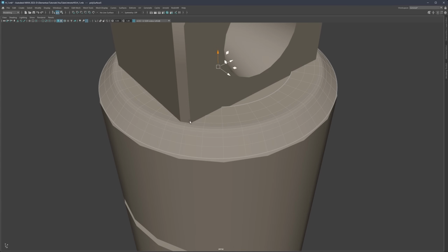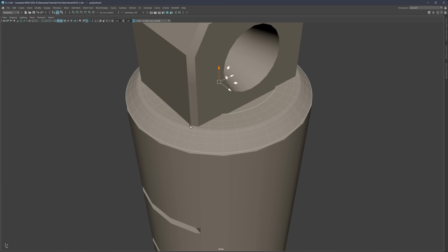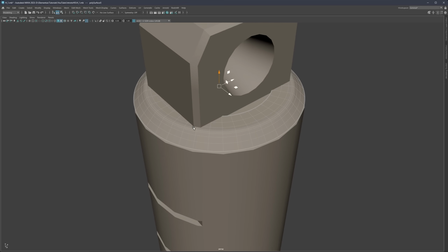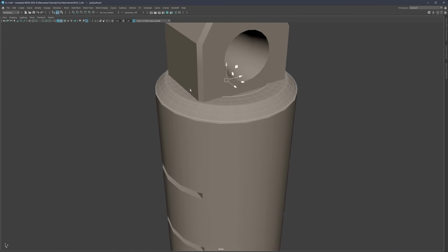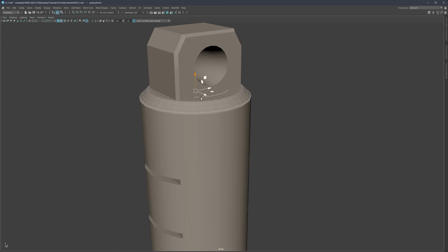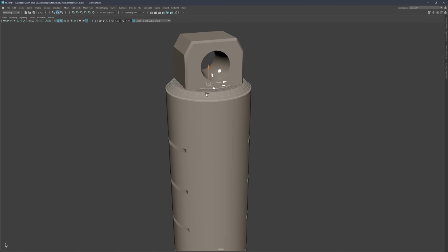And if you remember, what was the distance before that we established, that we need to have this corner sharp. So 40 might not be enough. We started with 20. When we're creating this form we can start now around 28 sides, or maybe even 24. 24 may be just enough to give us enough topology to maintain this shape right here at the corner. So again, it's a two-way street: we can start actually from here. This can be our beginning.